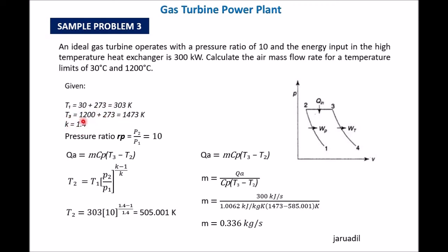For this one, I use the K value of 1.4. It is not given, so I will just use that. You can also use other values, you just have to justify that. But in our quizzes, my instruction is always that when there is no given condition, you use the standard values. For example, if the pressure is not given, or the elevation, you use the pressure at sea level, 14.7. The same with the value of K. If it is not given, you use the standard air, 1.4.